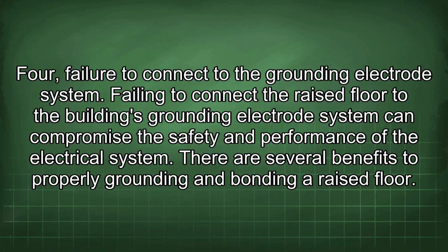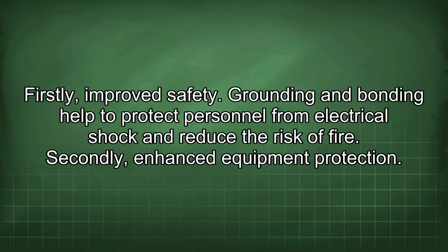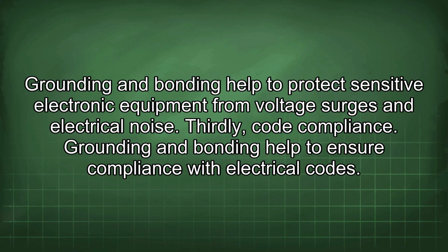electrical system. There are several benefits to properly grounding and bonding a raised floor. Firstly, improved safety. Grounding and bonding help to protect personnel from electrical shock and reduce the risk of fire. Secondly, enhanced equipment protection. Grounding and bonding help to protect sensitive electronic equipment from voltage surges and electrical noise.